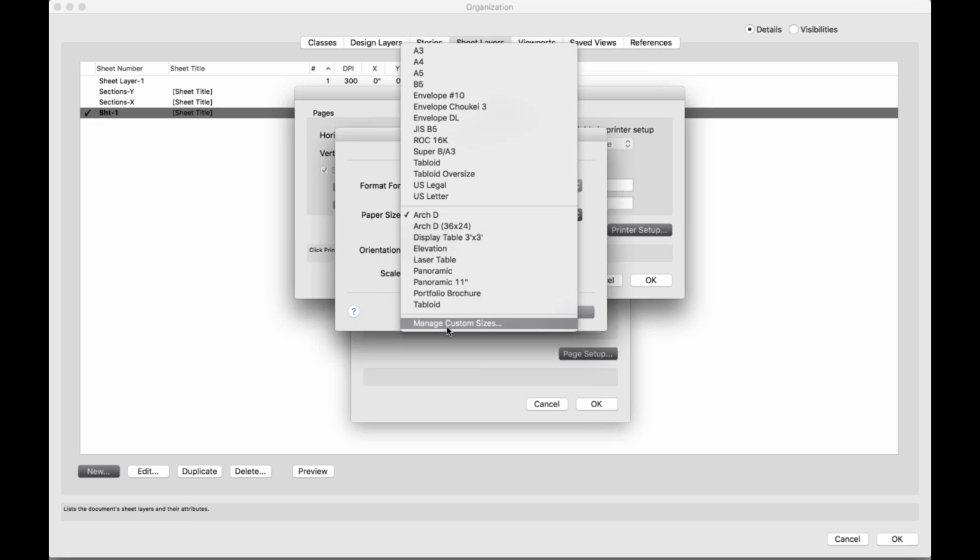If you want to see how all of these panels actually lay out on a standard 4 by 8 piece of plywood, then you can create a 4 by 8 sheet here in Vectorworks and lay out all of the viewports at a 1-to-1 scale within that one.